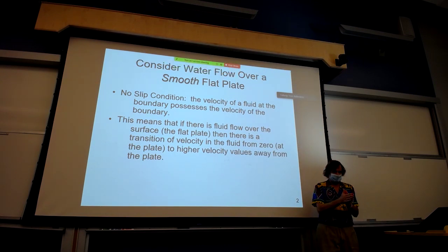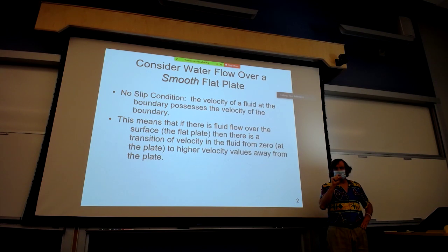And so instantaneously at the leading edge, you have one fluid molecule at 0 and the other one at capital U. And remember, the change in velocity over distance is the velocity gradient. And that's proportional to shear stresses.